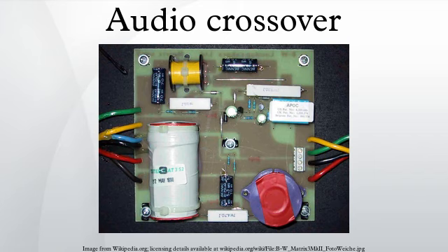They are not only frequency-specific, but also impedance-specific. This prevents interchangeability with speaker systems of different impedances. Ideal crossover filters, including impedance compensation and equalization networks, can be very difficult to design, as the components interact in complex ways. Crossover design expert Siegfried Linkwitz said of them that the only excuse for passive crossovers is their low cost.